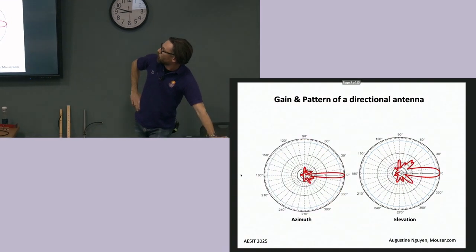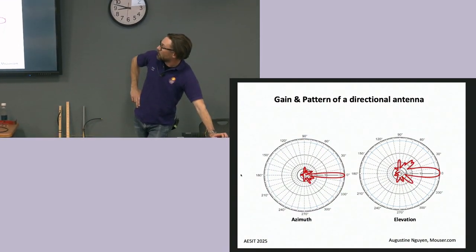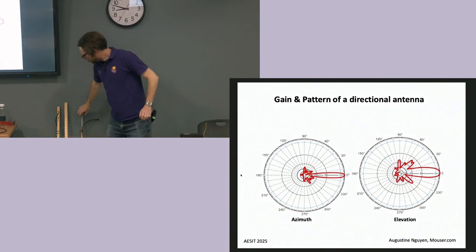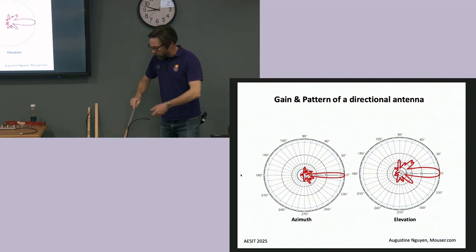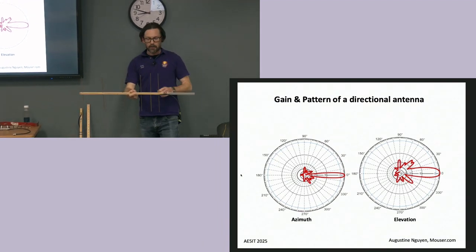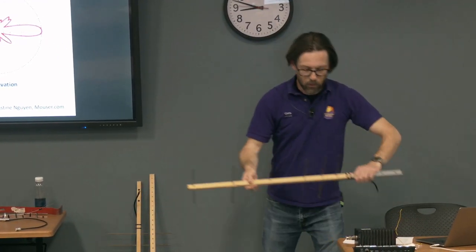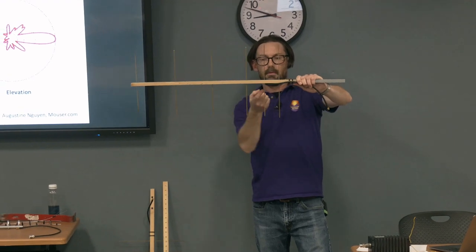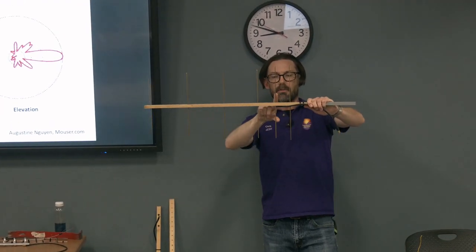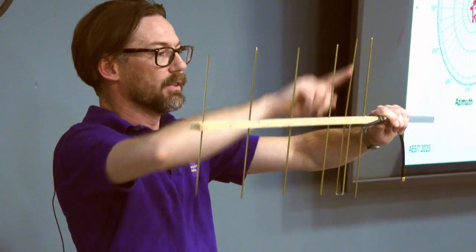And then another pattern we want to look at is a Yagi, or other beam directional antenna. With a collinear, we took 2 dipoles and stacked them end to end. Here we have one dipole that has the cable coming to it. This is our driven element. This by itself is just a dipole.